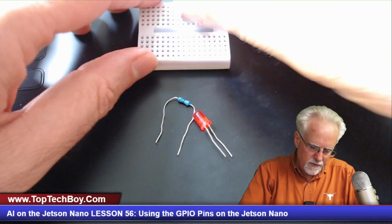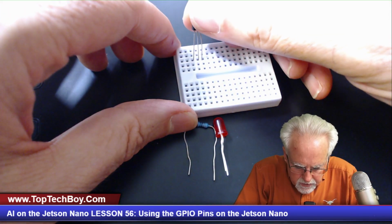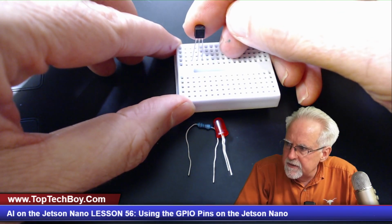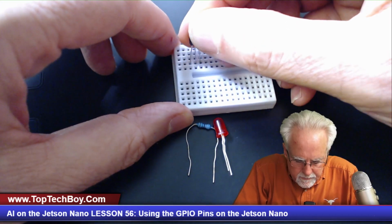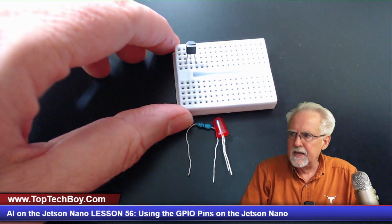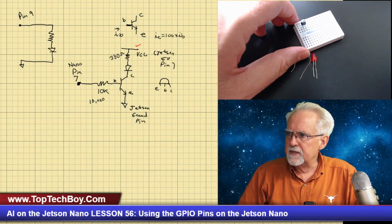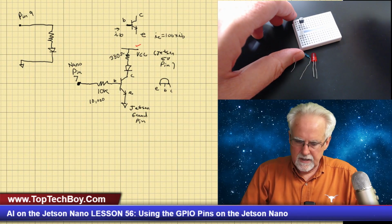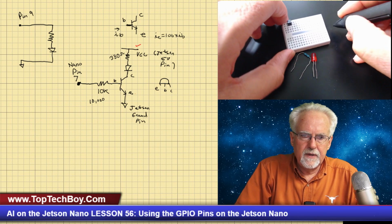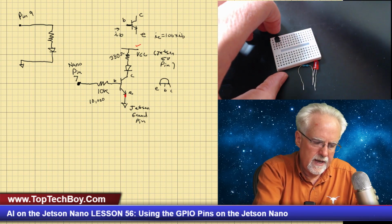So what I'm going to do is hook this with the emitter to my left. So I'm going to put this with the emitter to my left, so that means the flat side is towards me. And I'm going to kind of start on the left side of the board. All right, and so now if we go back over to this view so that we can see the circuit, you can see that the emitter, right here, the emitter goes to the Jetson Nano ground.